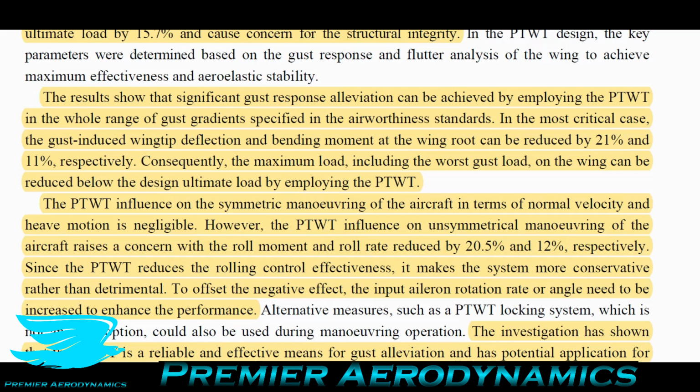That means that you can make the aircraft lighter and also make it safer, which is good for range, fuel economy, and ride comfort for the passengers. You don't want to shake them around like they're in a paint shaker. You don't want their brains scrambled. You want them to be nice and happy. They say, consequently, the maximum load, including the worst gust load on the wing, can be reduced below the design ultimate load by employing these wingtips.